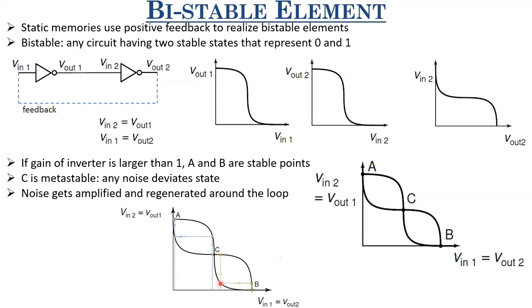It's this. Now, what is this V out 1? This is the input of 2, right? This is this value. This is the input of 2. Now, if this is the input of 2, what is the output? We'll look at the intersection at this. So from here to here, we'll draw a line and it intersects at this point. So this now becomes what? This becomes V out 2. And this voltage is what? This is the input of the first inverter.